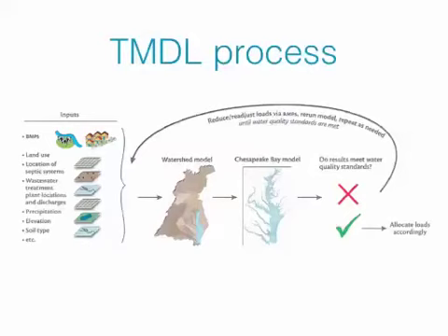So the process is taking these different inputs, these different best management practices, using a land use map, and then the various point sources and then non-point sources to drive a watershed model, which then determines how much nitrogen, phosphorus, and sediment is coming off the watershed into the bay, and then the bay model that then processes those nutrients and turns it into dissolved oxygen parameters, and other chlorophyll and the other predictors that model generates.